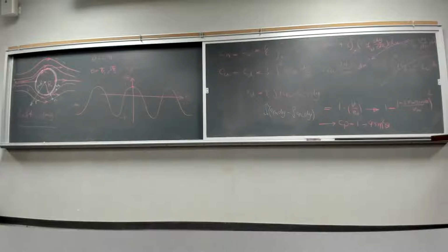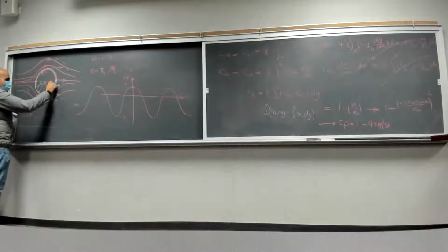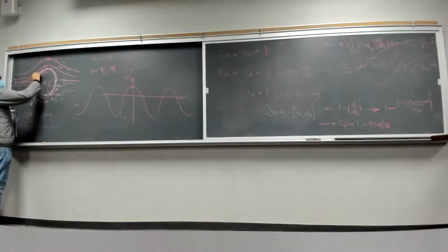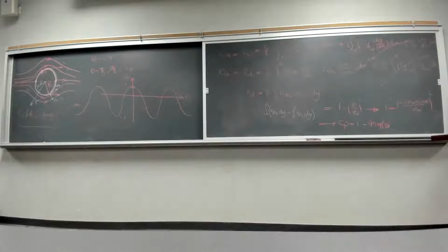It's going to give us the force in this direction. We are doing the same thing for lift. The only difference is that we are calculating the pressure force on this surface and then subtracting it from the pressure force on this surface. Does this make sense? Okay.